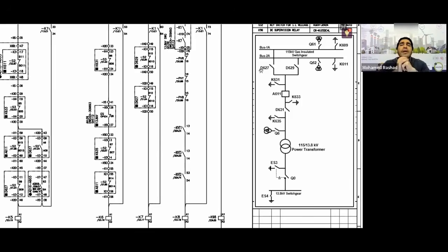Okay, so now I'm completely sure with you that I cannot open this disconnector or operate it under load. Can you explain this a bit more so that I, as an electrician, can understand you better instead of feeling like it's just a general story? I'll tell you. The point is that the disconnector should not be opened or closed under load, meaning there must be no voltage difference between the terminals of the disconnector.